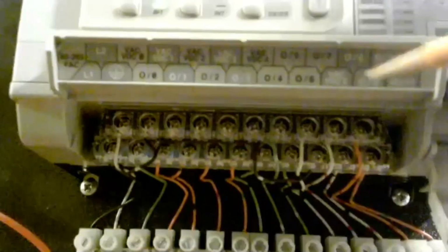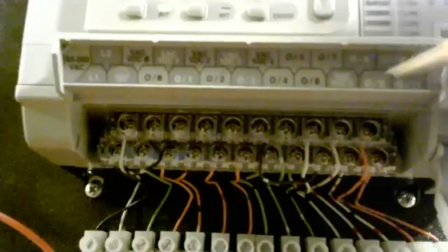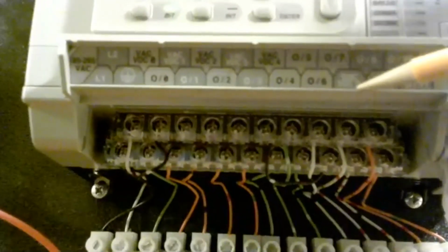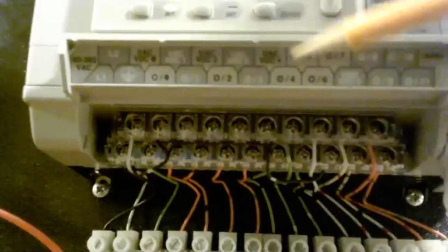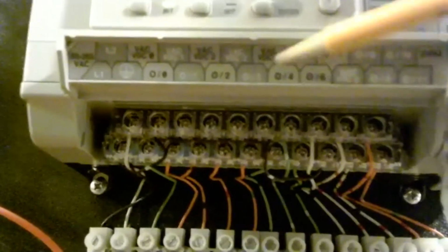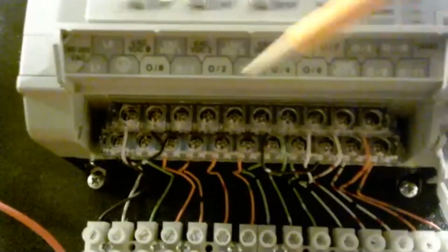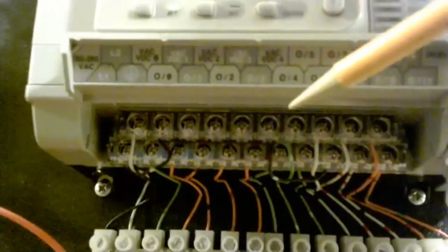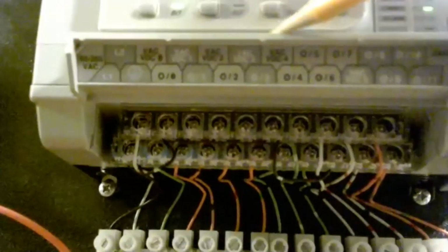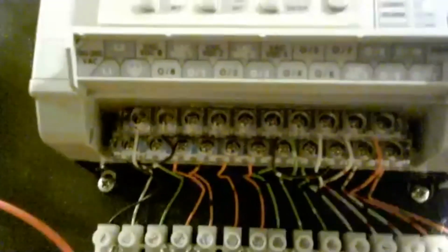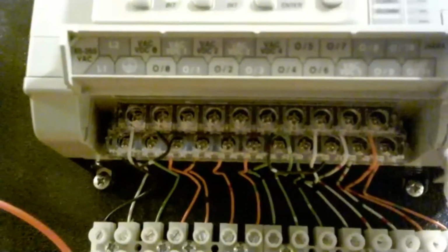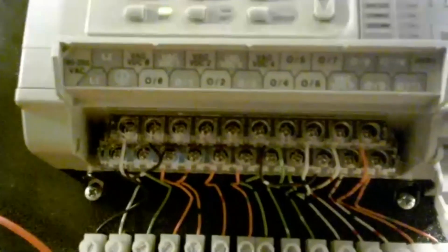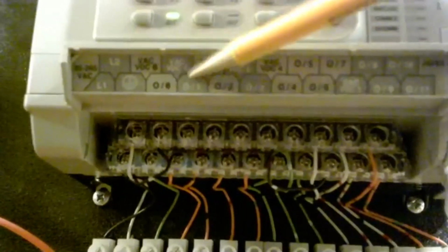So they are individually controlled in the program, but they get power source from that one terminal. But you could put AC on this one and have a group of AC outputs. You could put DC on this one and have a group of DC outputs. Everything before it has their own individual power leg. And I don't know why in the world they designed it that way, but that's just what it is on this model, on that particular type of MicroLogix. And so there are jumpers up in there that jumper a 120 volt to every one of the VAC terminals.